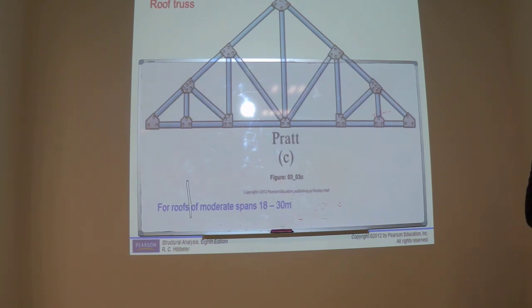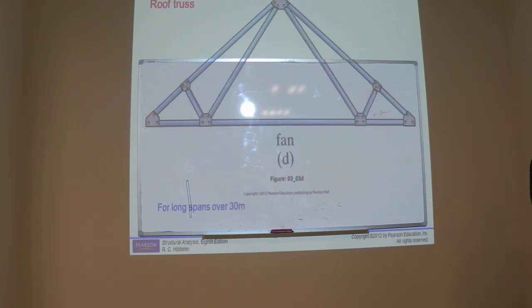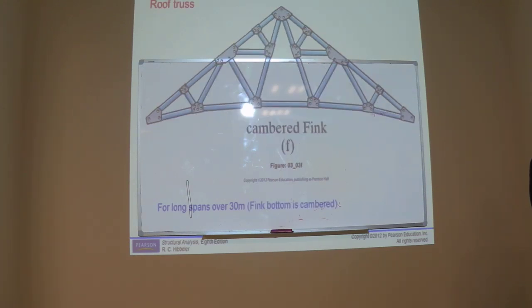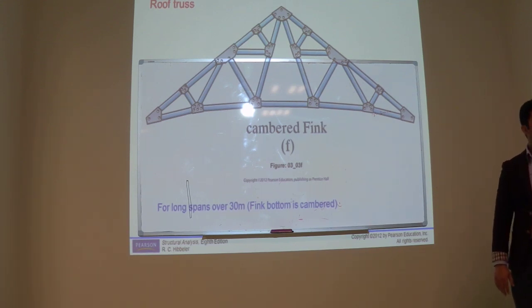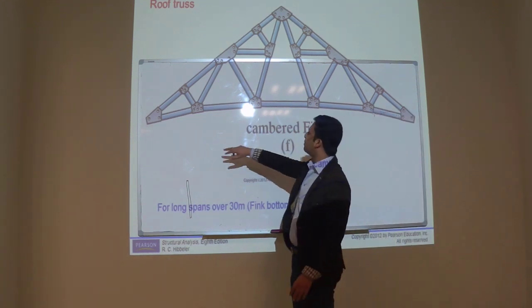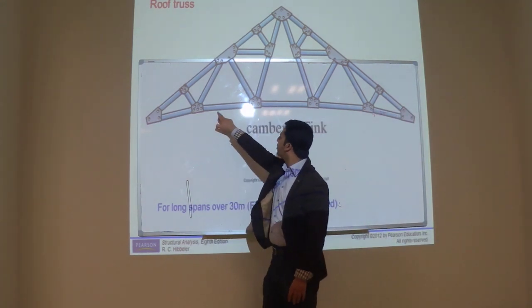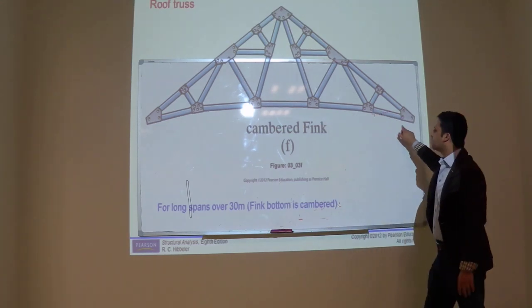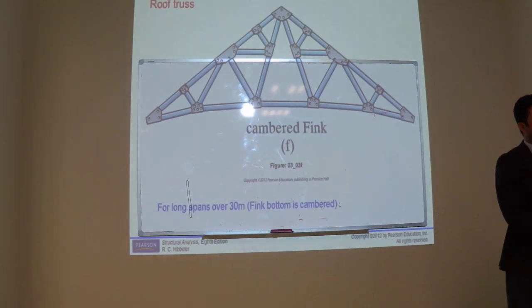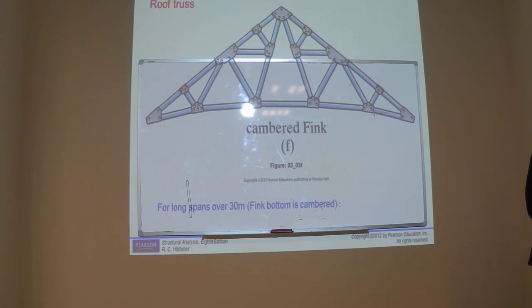Pratt, fan truss, Fink truss, cambered Fink. Cambered Fink, why we call it cambered Fink? Because we have lifted up the bottom chord. If you see the bottom chord, we have given a camber. Camber means we are going to lift some part. Why we give camber?